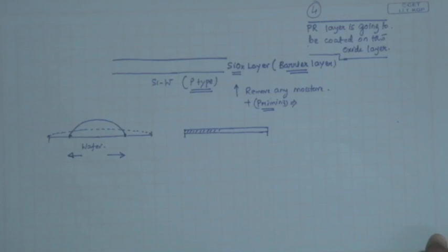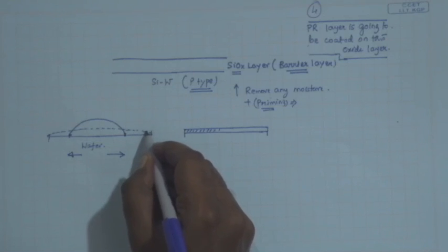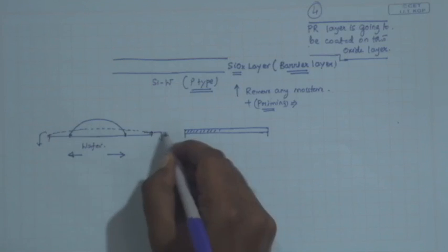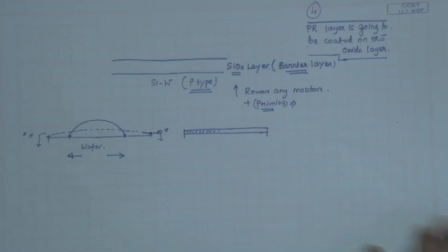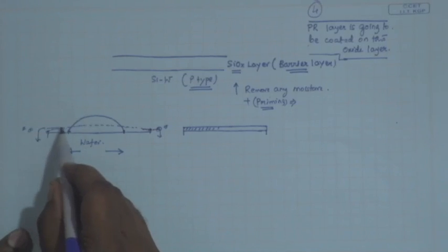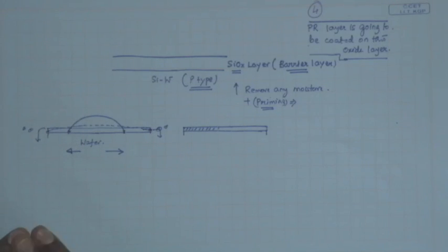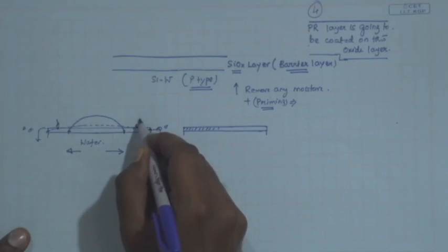There is no guarantee that it will spread only up to the edge and not beyond, and that is exactly the case. As you start rotating and the meniscus reaches the outer periphery, a significant amount of the solution is thrown out and wasted. Second, you typically use a solvent that evaporates rather fast. What is the rationale? You spread the solution layer over the entire surface, and simultaneously, while the substrate is still rotating on the spin coater, you want the solvent to evaporate away.